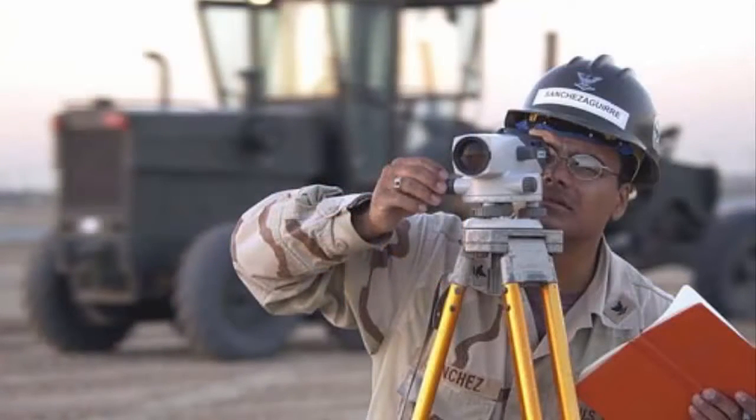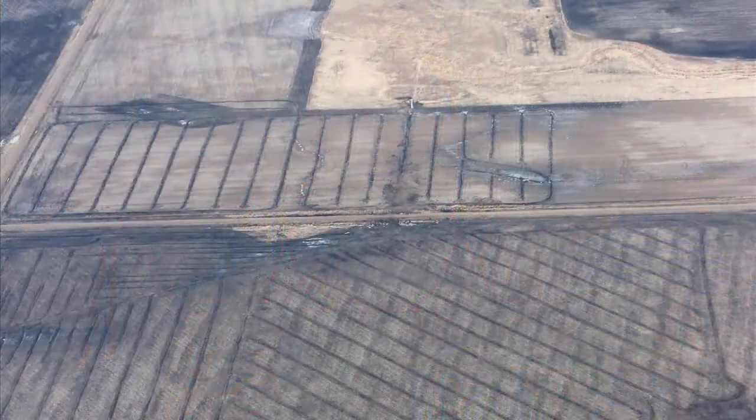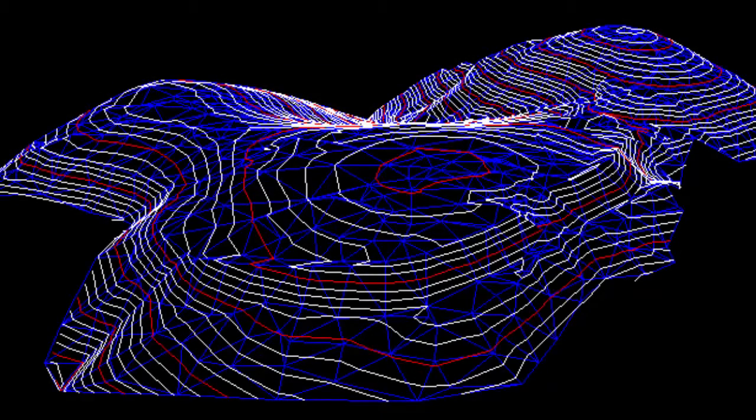A mapping survey collects the information we need to make maps. Maps can be enormously valuable for decision making. For example, in modern agriculture, we can use maps to analyze the shape of the land surface and to plan drain tile systems like you see here. We pay close attention to surface slope to produce efficient, reliable systems.